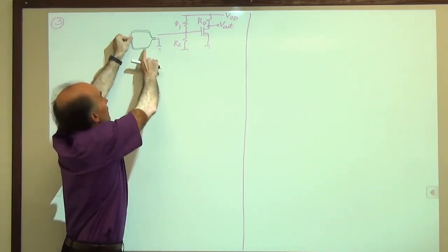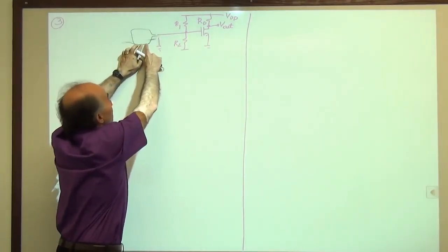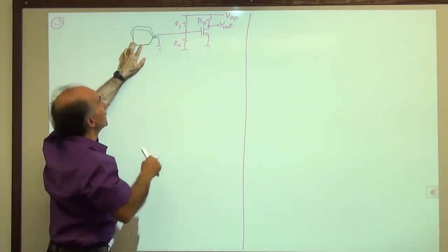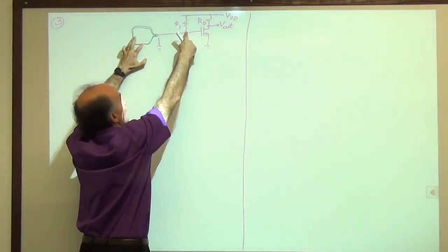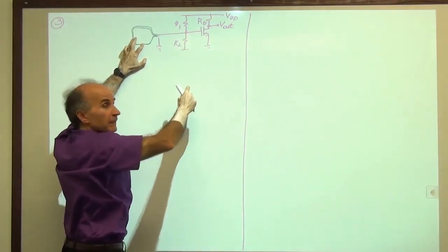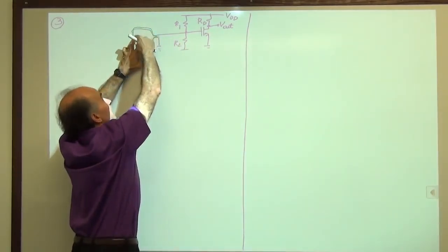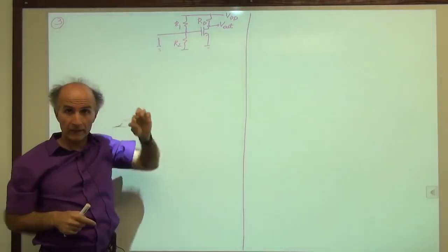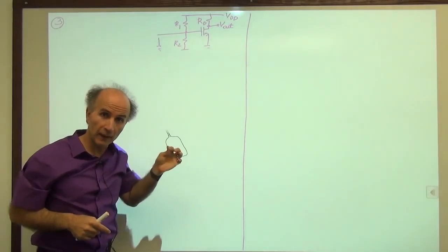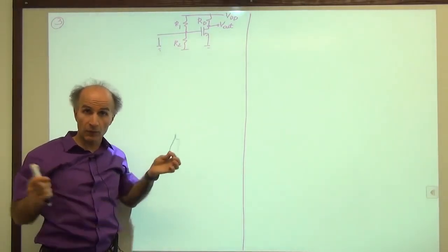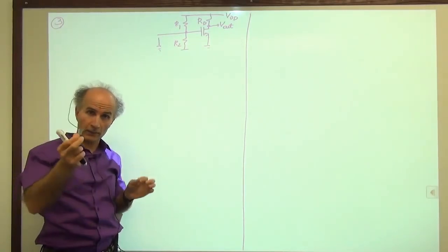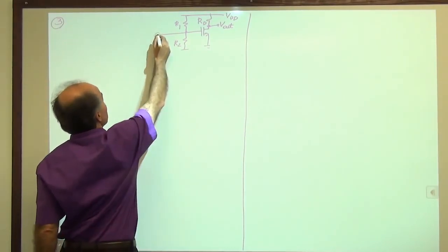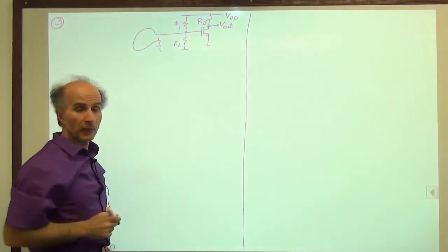Okay, so if you look carefully, this is what we see. Before the antenna has any signal, do we have proper bias conditions? You can see that this node, which was supposed to have a voltage of V0, now goes through this wire and comes to ground. In other words, the antenna is creating a short circuit between the input of the LNA and ground in the absence of signals, right? This is just a piece of wire. When there's no signal, this is just a piece of wire. So what the antenna did was short the input to ground.